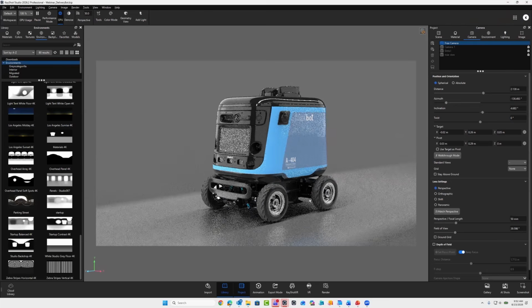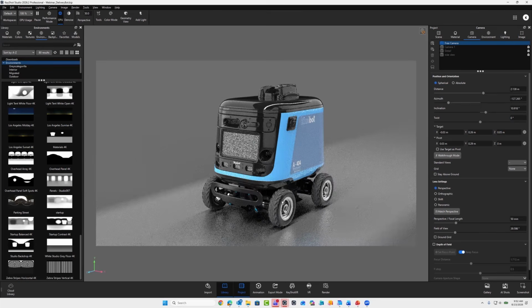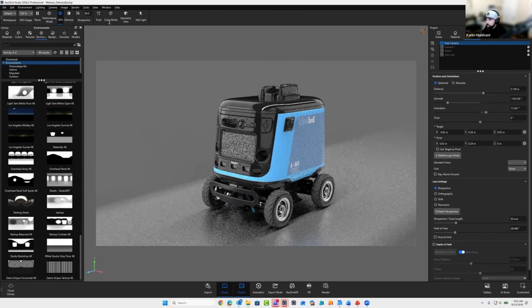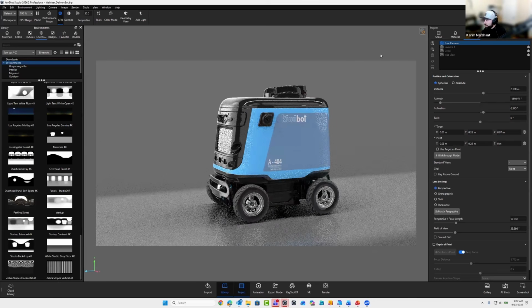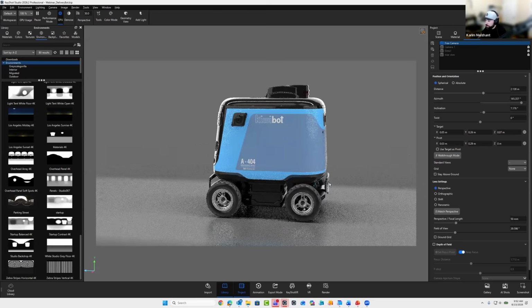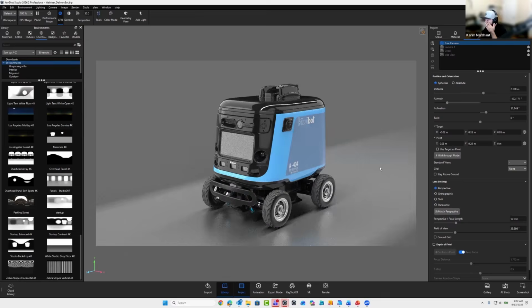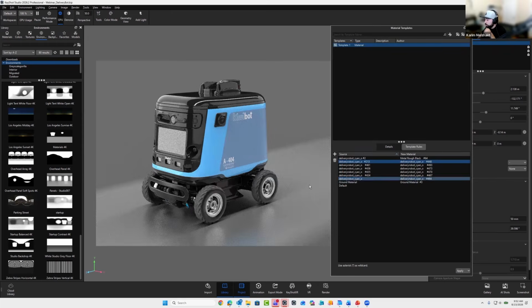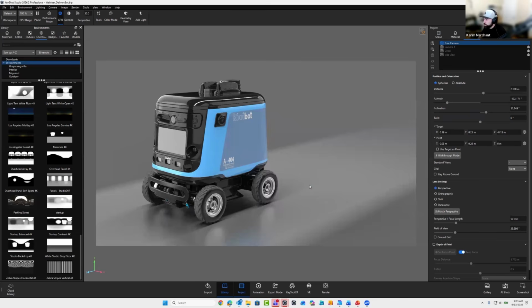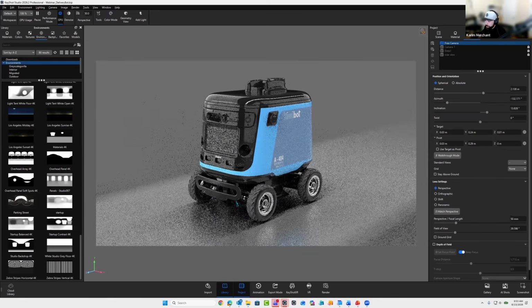Let's see. Do you have any recommendations for setting up preset scenes and materials to improve workflows? Yeah, again, the material template that we were talking about, being able to set up the information from your CAD source, whatever the naming convention is that you're bringing it in with, and then being able to apply those materials as a correlating material in KeyShot. That's incredibly easy. You can also set up templates for your scene, not so much for materials, but you can create an environment that's already staged with your lighting, and that way when you bring in your model, you still have to materialize it.